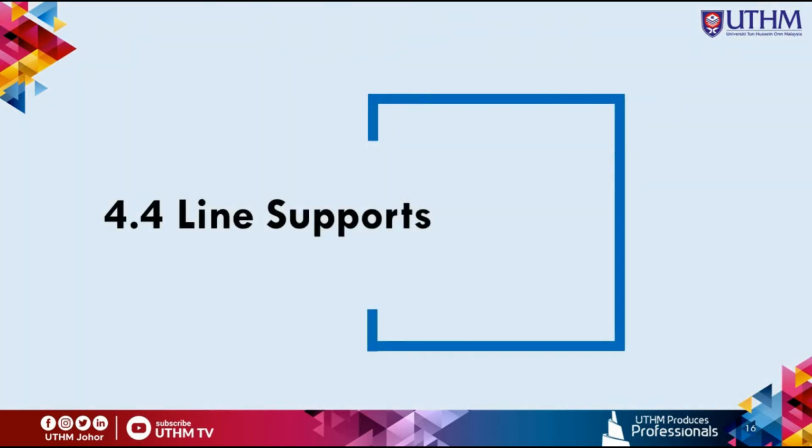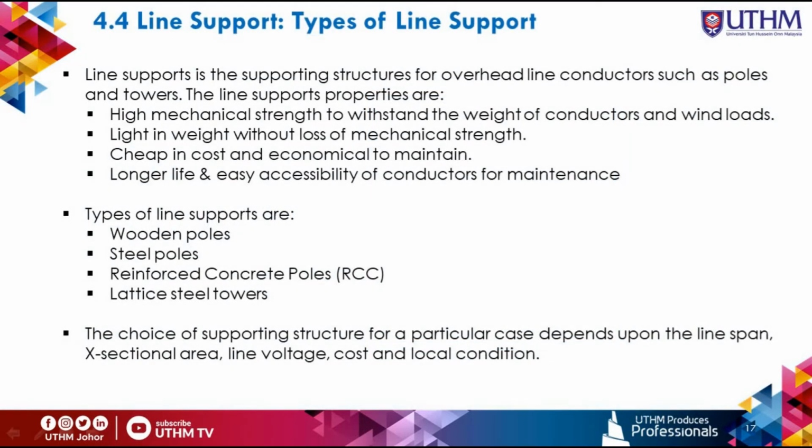Okay, next is the line supports. Line supports are the supporting structures for overhead line conductors, such as poles and also towers. In general, the line support should have the following properties. The first one is high mechanical strength to withstand the weight of conductors and wind loads.